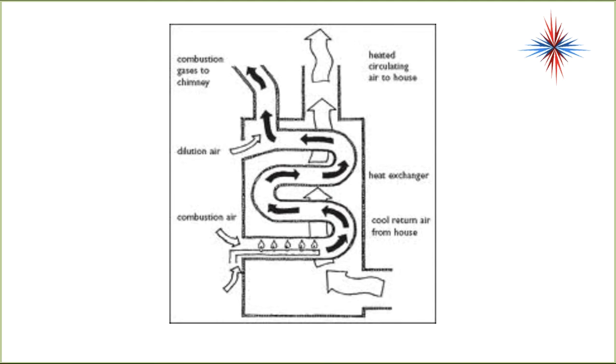So this is the inside of, let's say, a gas furnace. I know it's not the best diagram, but we have our combustion side, which comes across the darker black arrows, and then we have our air side, which blows across. This is our heat exchanger. The combustion and the air will never mix, and that's very important. The combustion air, in the black arrows, will never come in contact with the circulated air, the return from the house and the supply to the house.